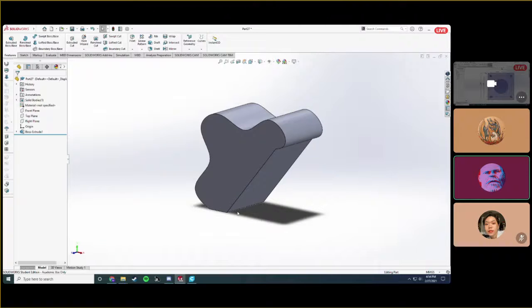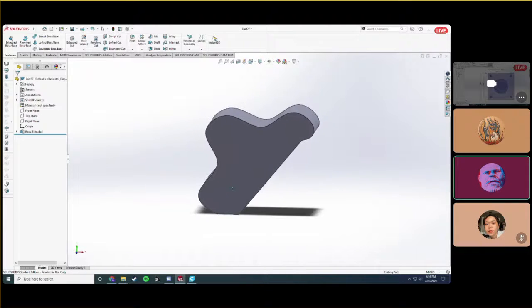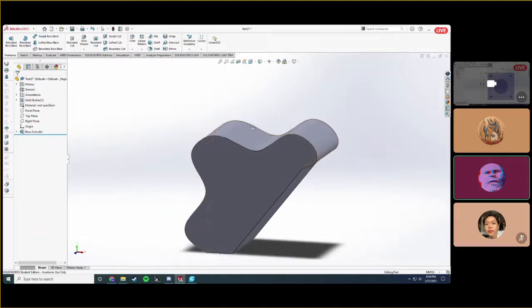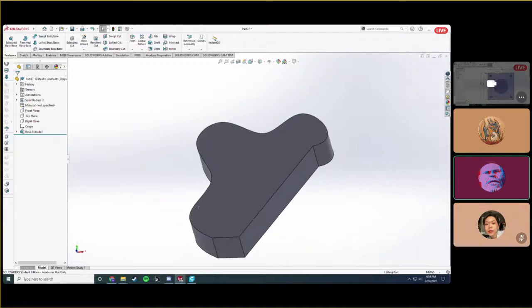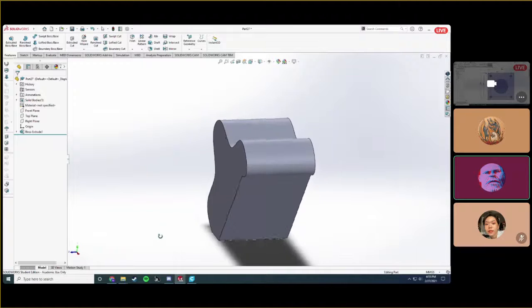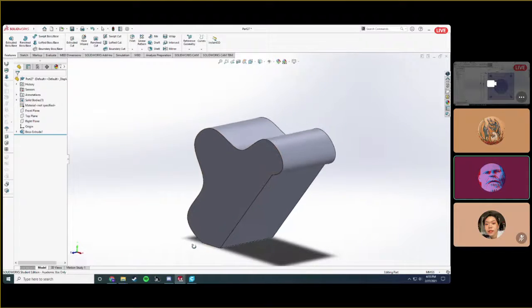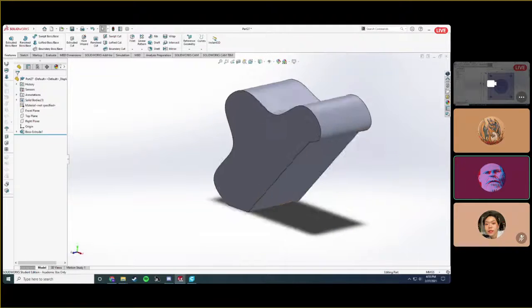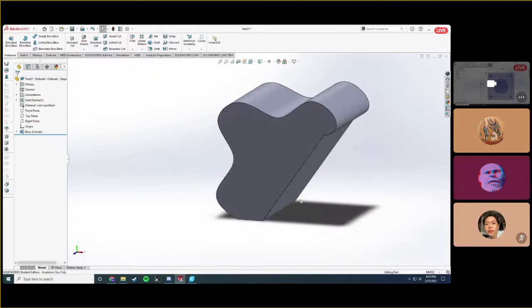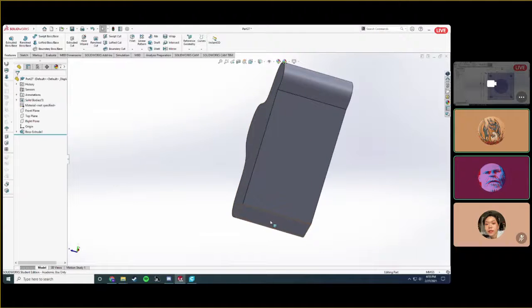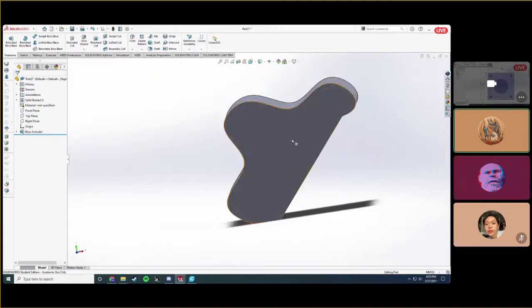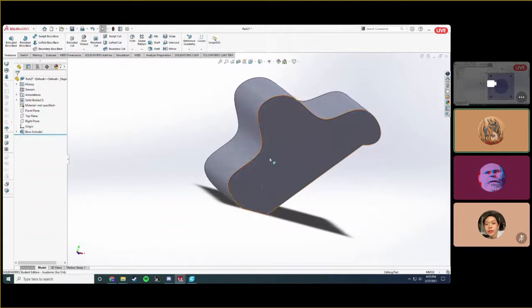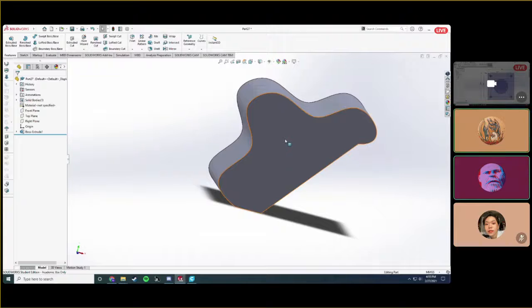It'd be weird, yeah. A lot of the time when you're printing something and you don't have a lot of surface area connecting your part to the build plate, and it's a big part, it might fall off the build plate while it's printing, especially with a Cartesian printer, because the bed is moving back and forth. If you were to flip this, there's not a lot of space actually touching the build plate and it's a big overhang, so there's a good chance it's going to come off the build plate while it's printing and fail. So if you go to the slicer, show them how to set build plate adhesion like a brim.